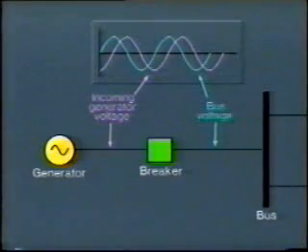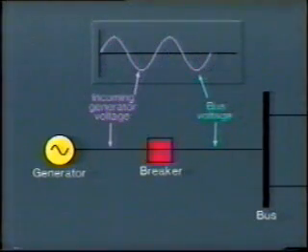You can see that the generator is over 90 degrees out of phase. If we closed the breaker in this condition, the generator would attempt to pull itself into phase. This could twist the windings and the stator core and create considerable damage. Of course, the great surge of power would be detected and the breaker immediately opened by protection devices.